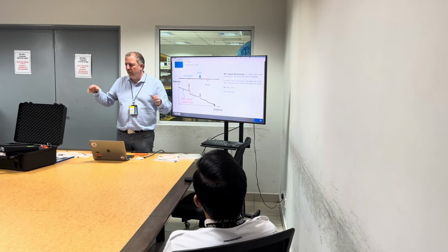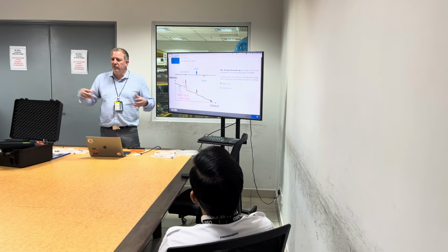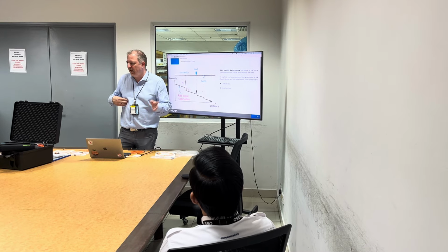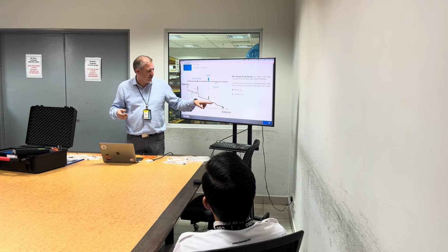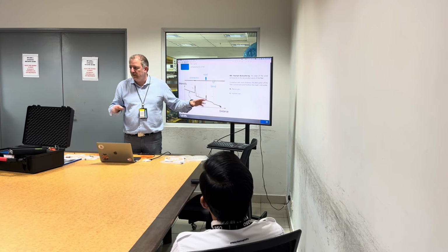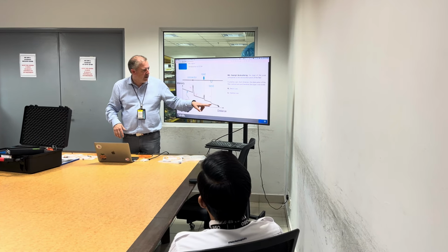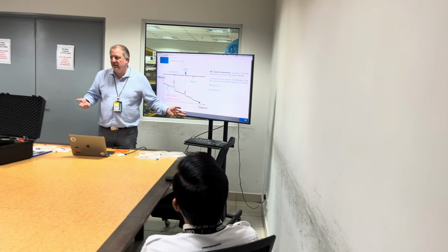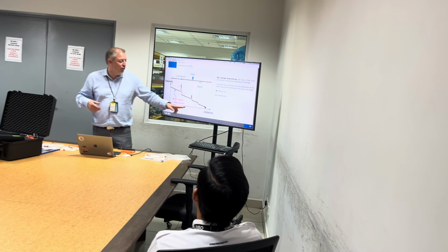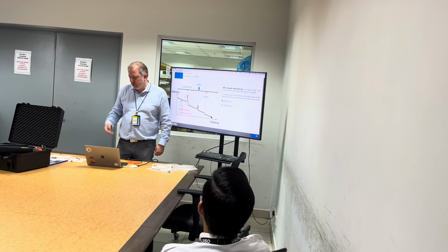It will mostly propagate into the air outside, or into the shield, the protection, or whatever. But you don't see that light anymore. It's gone. And usually at the end you have something crazy with a lot of reflectance, which is the end of the fiber. It could also be on equipment, so I'll show you some examples.